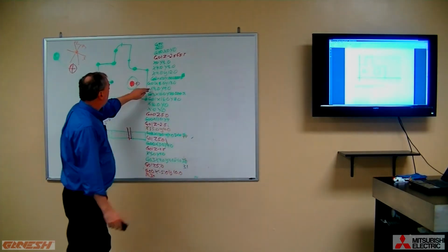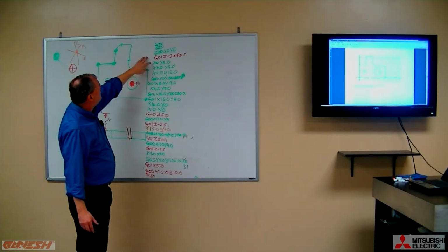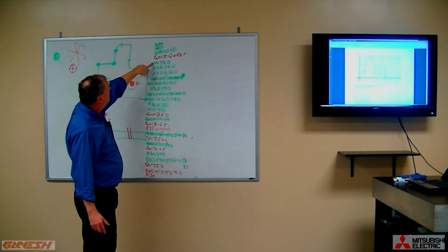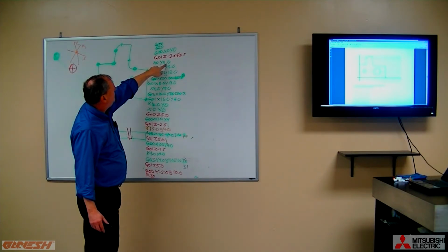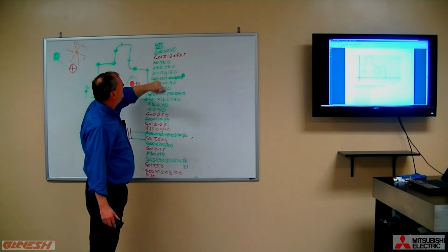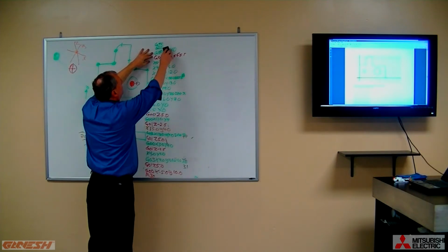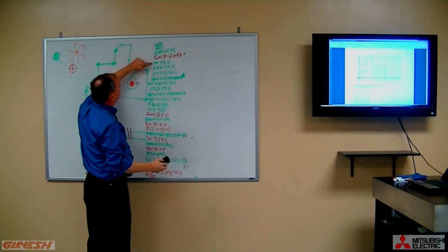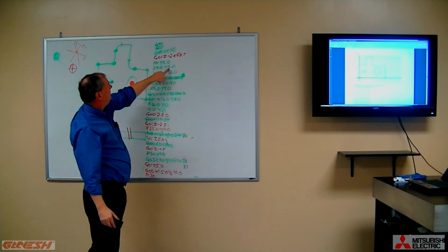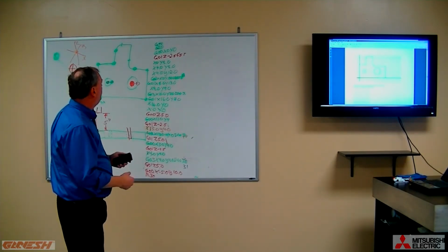So now I want to talk a little more about the modals. Take a look at this block here that we did. We're going to X0, Y8.0. Before that, we went to G00, X0, Y0. Now, what's the same here? The X0, and then the X0 is actually repeated again. Here, the Y8.0 is repeated. We don't need to repeat those numbers. Those are modal as well.